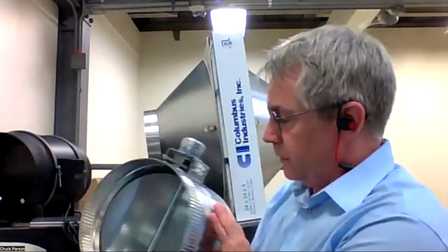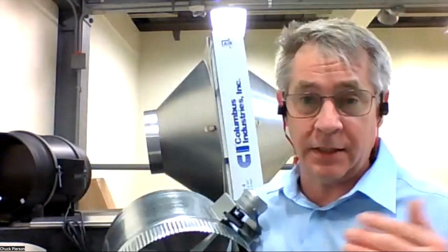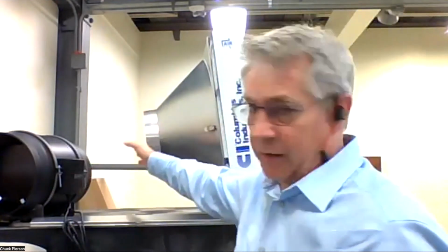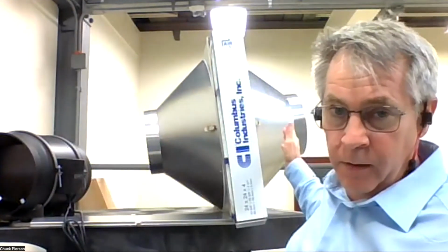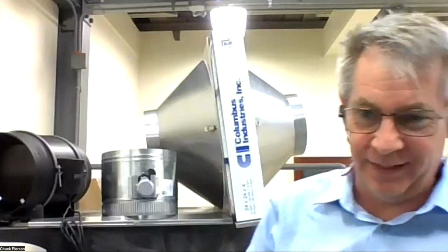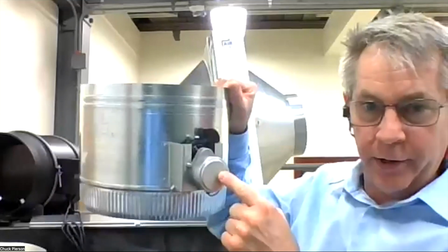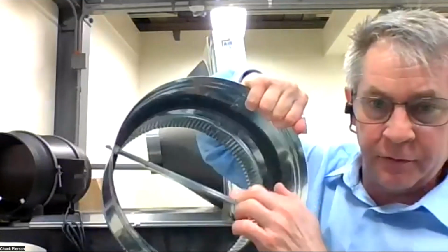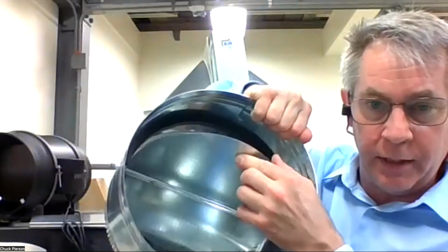And then this is just the damper that we're going to use, because it is a temperature vacuum swing device, we need to be able to seal off the inlet and seal off the outlet when we're in desorption mode. What was that? I said it's a valve. I didn't used to know what a damper was until I looked it up. Yeah, it's a valve. It opens and closes, lets air in, blocks airflow. Yes, thank you. This is an actuator, and it's just motor driven with 24 volts, and it turns this shaft to open and close that and make an airtight seal.